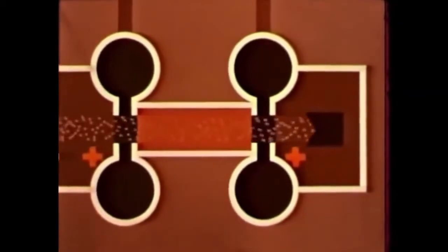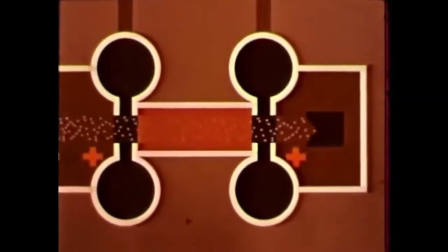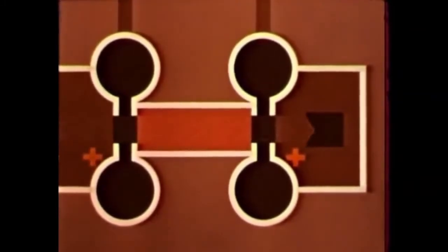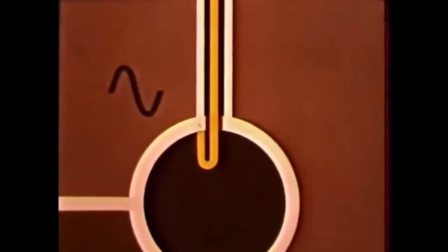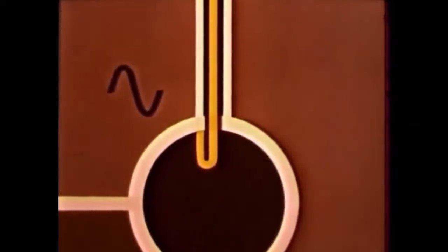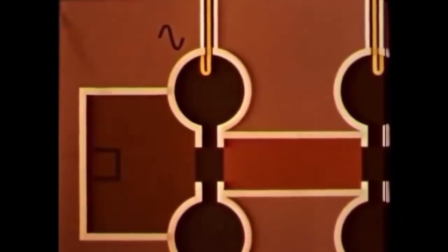Therefore, in the region between the first resonator and the collector, the electrons would have a constant speed if it were not for the influence of the cavity resonators. In reality, the first cavity resonator is supplied with the weak high-frequency signal which is to be amplified. This signal will initiate an electromagnetic field inside the cavity.